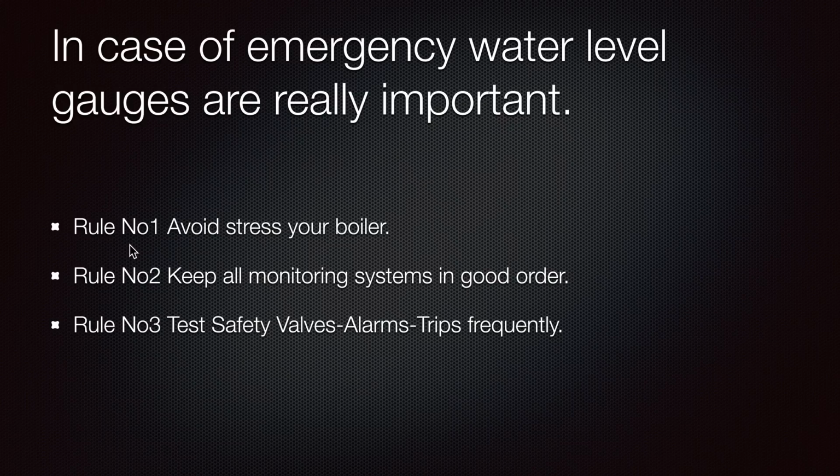Let's run through the rules. Rule number 1, avoid stressing your boiler, as we described in the beginning, by adding cold water quickly, or reducing the water level too low or too high, and try as much as possible to not put a big amount of water inside of the boiler and stress the material.